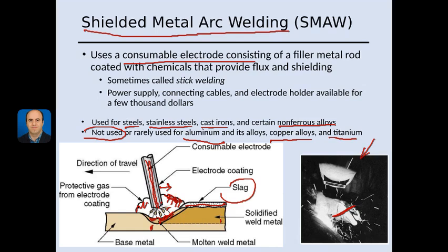It increases the production time. And if you use high current for the process, the flux may melt prematurely. So that's the next disadvantage of this process.